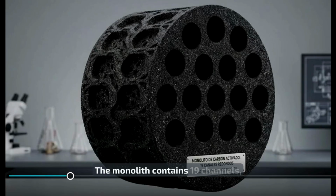The monolith contains 19 channels, with a hydraulic diameter of 15 millimeters and a required area of 0.1 square meters. At an airflow rate of 9.4 liters per minute, the system operates under laminar conditions, with Reynolds numbers below 50. Mass transfer coefficients were estimated using Sherwood correlations, confirming external resistance as the limiting step.